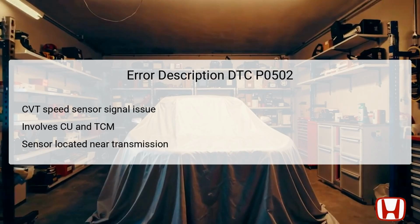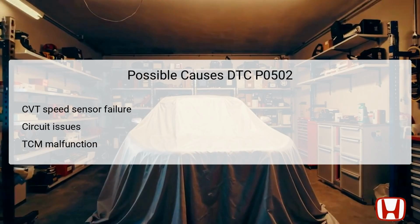accurate readings. When the TCM cannot detect the sensor signal, it might lead to suboptimal performance, including delayed gear shifts and potential engine stalling. Because accurate speed information is vital for engine management and performance tuning, this fault code necessitates prompt investigation. Understanding the role of the CVT speed sensor and its interaction with the TCM is crucial for resolving this issue effectively.